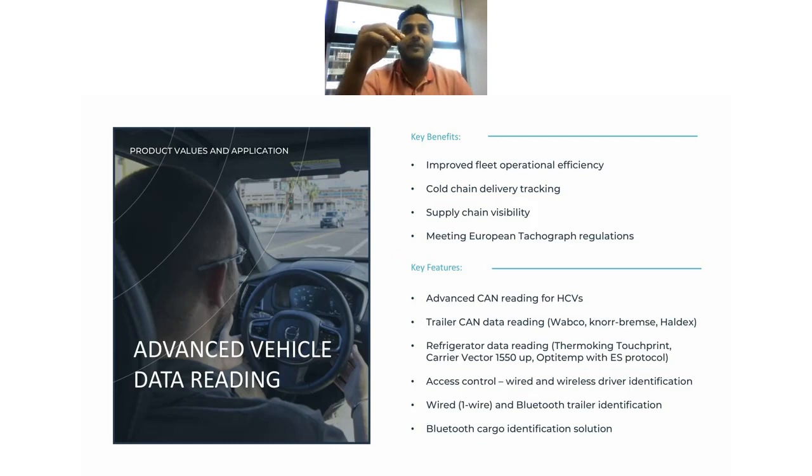If you go with OBD, you can see all the vehicles that are supported on the OBD line itself. When it comes to LCV, you will also find OBD, but you will also find vehicles that would not share data on OBD, where you will have to search for a different CAN bus line. All the installation diagrams for those vehicles will also be available on that same page. All you need to do is request our support team, support@ruptela.com, for that specific vehicle installation schema, and our support will be more than happy to share the schema with you,